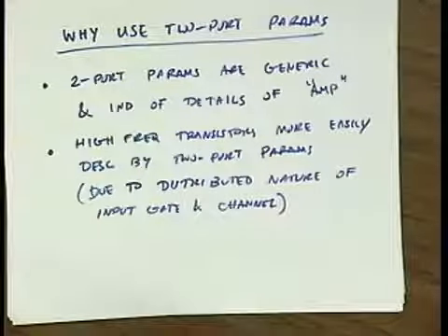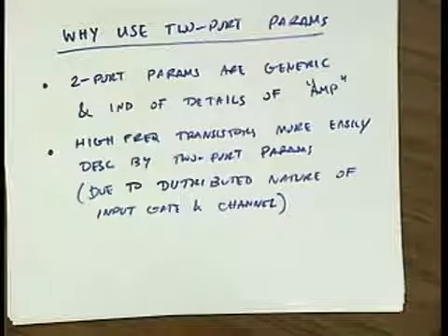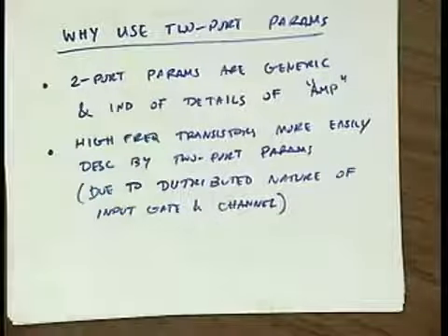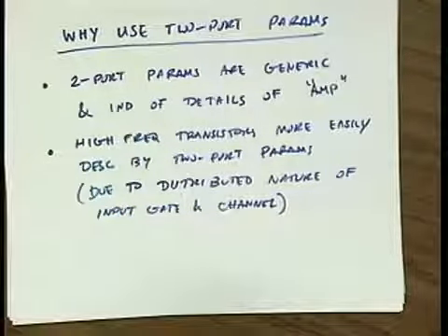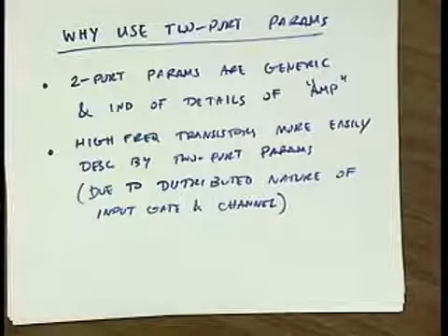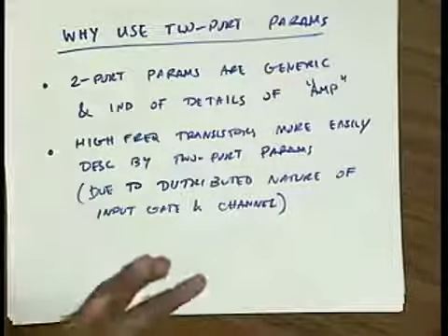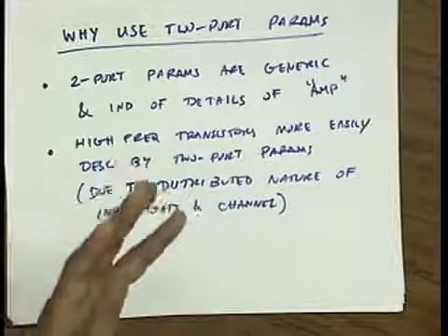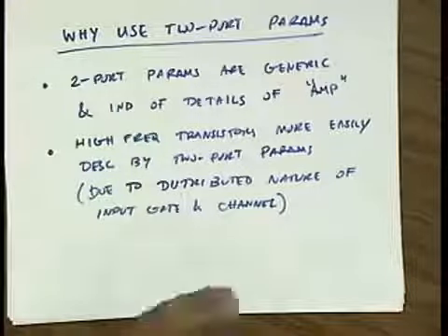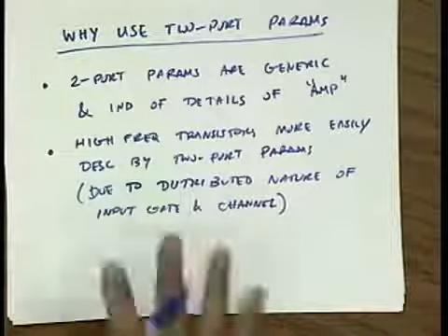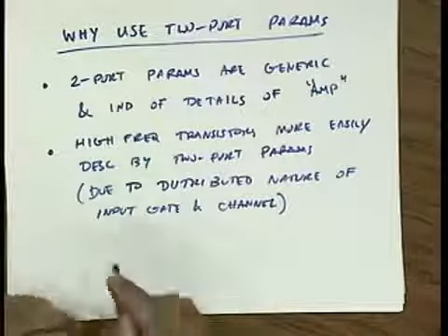And if you want to model the transistor at really high frequencies, it turns out, especially as the device becomes more distributed, it starts acting more like a transmission line. It's very difficult to write equations for that. You have partial differential equations. But you can always simplify that complicated transistor structure into 4 Y parameters. So even at really high frequencies where distributed effects have taken over, we can still have a pretty good idea of what's going on if we use Y parameters. Okay.